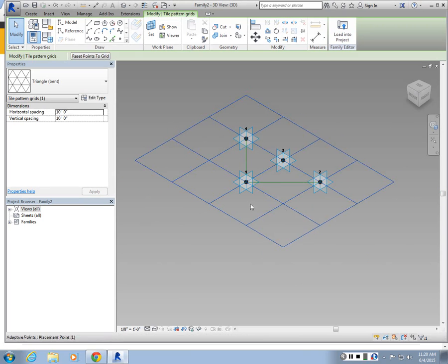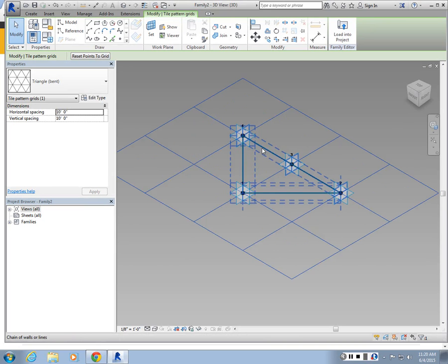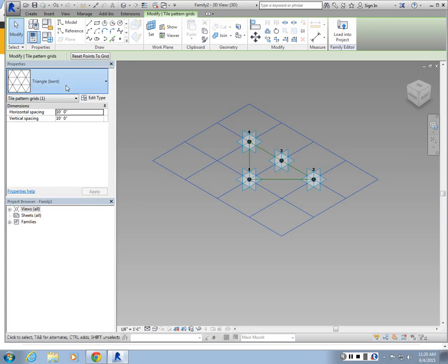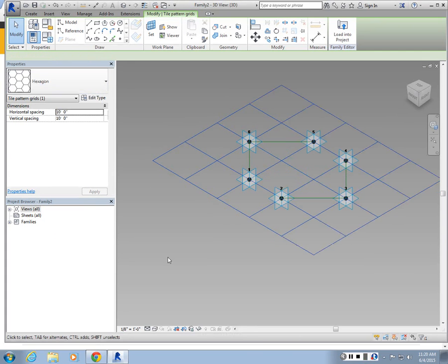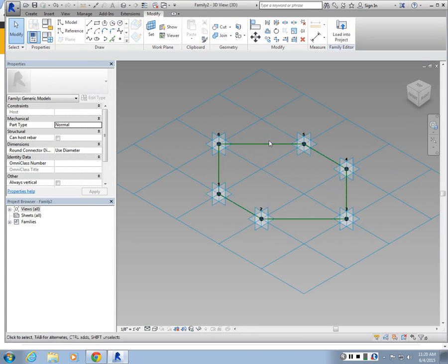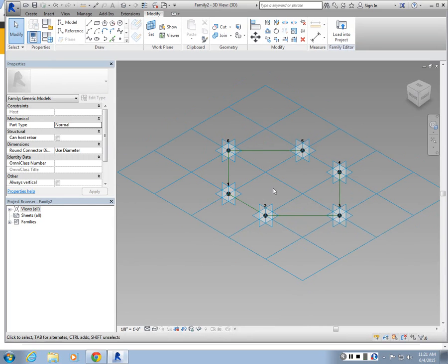It's showing me how much space this tile occupies within the surface grid, and how many control points it has as well. So the triangle needs 4 control points, but if I choose something more complex like the hexagon, it needs more space, right? It needs 2x3 grid space, and it has 6 control points, and these control points snap to the grid. Right, so this guy will be copied. There will be another version here, another version here, another version there. It will keep tessellating the surface. Does that make sense to everyone?